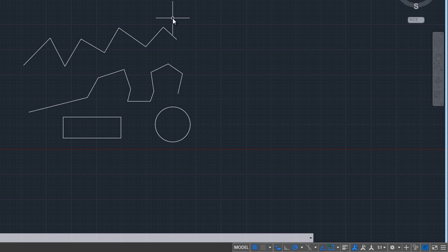So instead I've gotten into the habit of drawing a line off into the distance to a ridiculous distance, and we'll talk about entering distances in a little bit. And then I do a zoom extents command, and it zooms to that ridiculous distance. And then I delete the line, and then normally I don't have to do that again after that point. I may need to do it again, I may not, it depends, but rarely would I ever do it a third time. So it's unorthodox, yes.